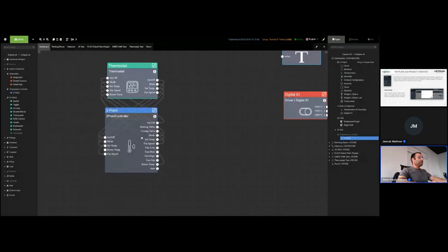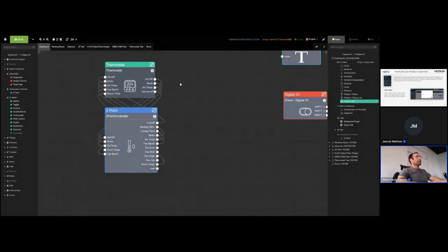So we need a relay module to control heating, cooling valve, and the fan low, mid, high, and top. So we need a module because we just did here a UI control connection.